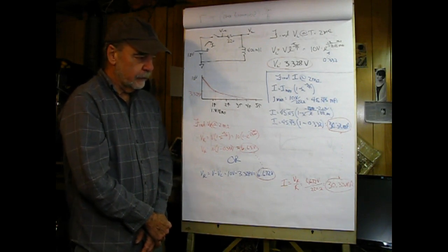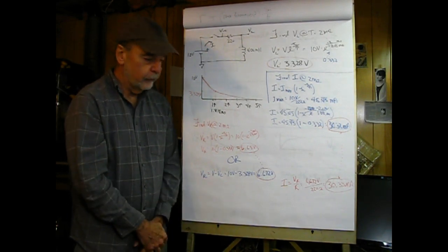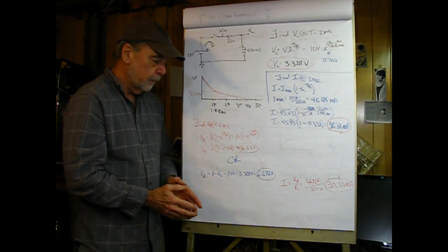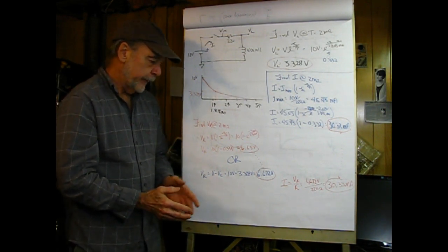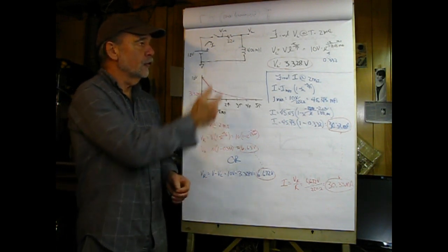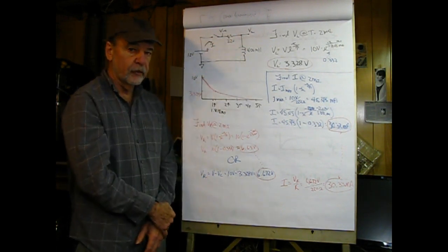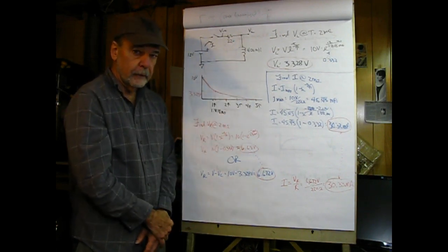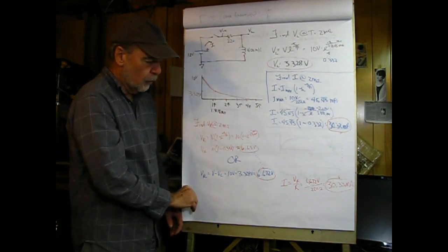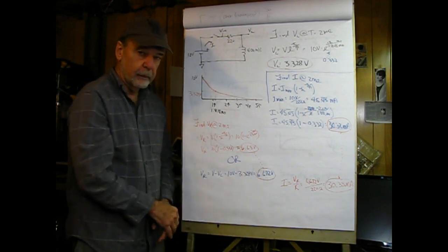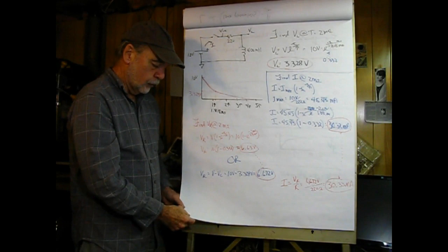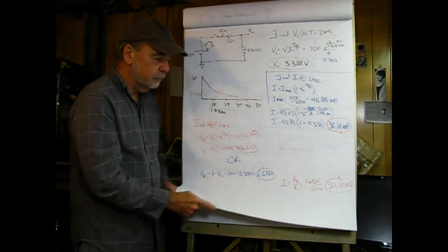So which is the right thing to do? Whatever is easier, whatever's less prone to error. And accuracy, well, our resistors here, tolerance is typically 5%. Inductors that we use are 10%. So small variations in voltage like this really become insignificant because of the tolerance, and that tolerance is also a function of temperature.